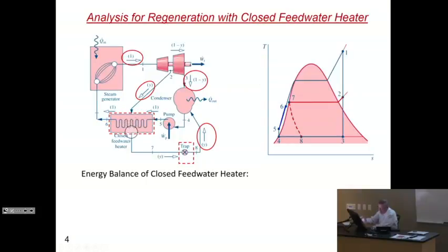That steam is condensed at point number 7, which is on the saturated liquid line. Then it's sent through a trap. The trap is a thing that keeps the enthalpy constant but reduces the pressure. So an isenthalpic line on the TS diagram looks like this dashed line here. The work of the trap is going from 7 to 8.